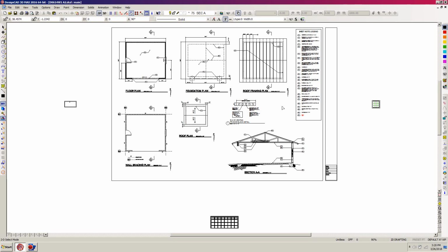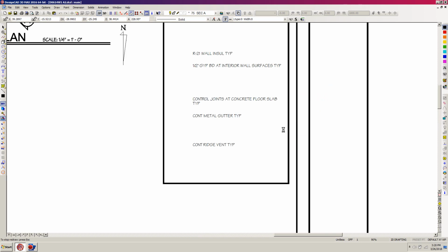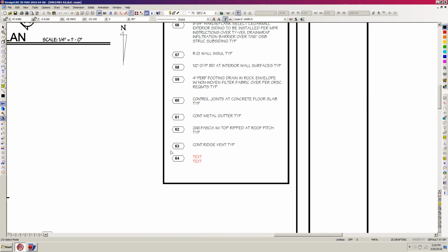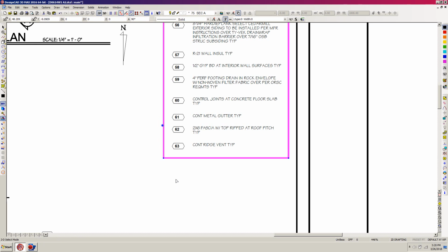and get rid of the slash sheet note, hitting Z for zoom. This was just a spare that we were holding in place in case we needed to add any additional sheet notes. So I'm just going to select these using a rectangular selection and hit delete. And now I'm going to select my border around the sheet notes legend and select these 2 points at the bottom. Hit H for orthogonal mode, and right click on one of those points and just move it up until it looks like it's in a good place, and then clicking, and it's taking care of that.